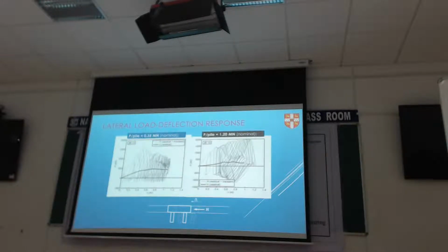Also, the accumulated displacements for the same earthquake, these are getting up to more or less a meter. This is a bit more. So although the residual component is smaller in terms of load, you are going further to one side at the end of it all, which means this is the effect of the P-delta.